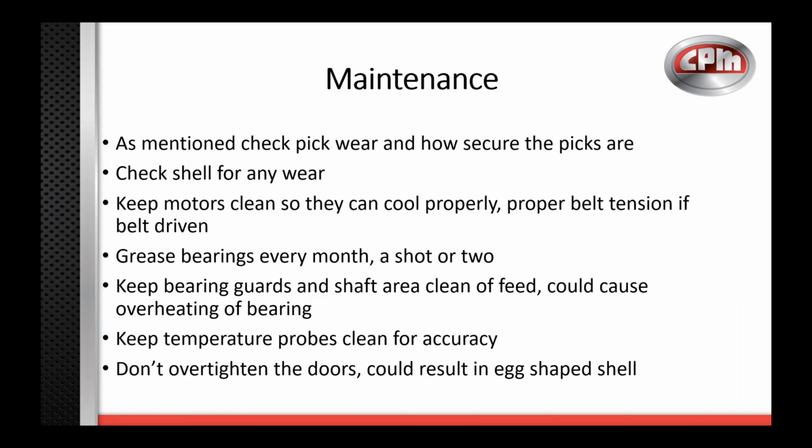So we're going to wrap things up here today with some minor maintenance issues or things to look for. A lot of this is probably just everyday practice, but it's still good to have a refresher. As I mentioned, we want to check our pick wear and how secure the picks are. I've actually been to a location where the pick wasn't tightened down, and so as the feed was flowing through, it just went with the flow and wasn't being utilized, so it's kind of pointless, that individual pick.